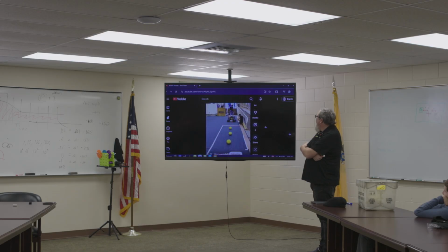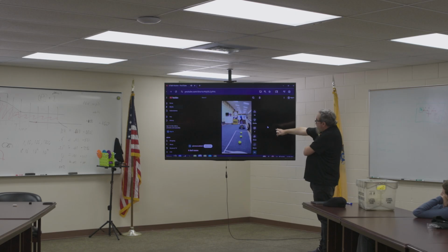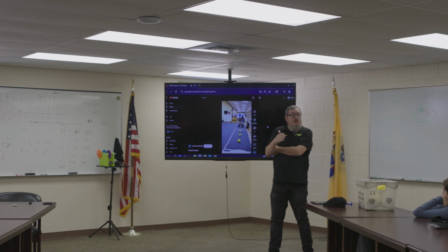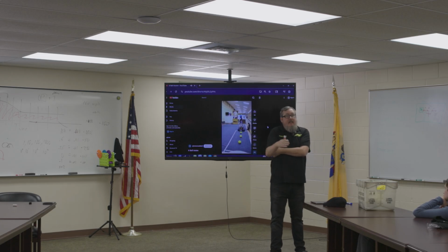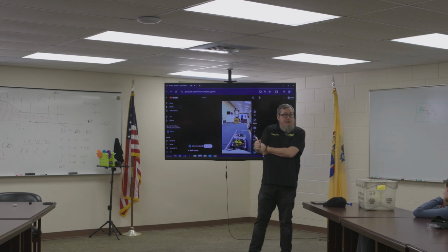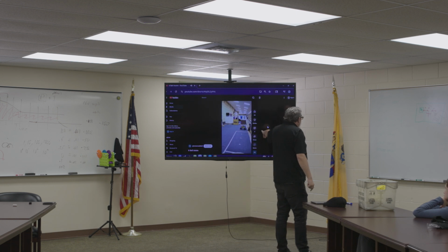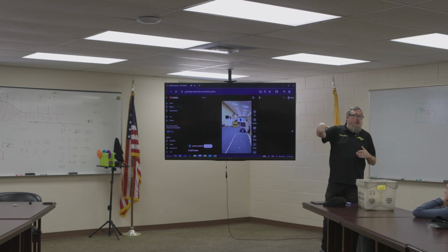So this is using a trapezoidal motion profile, so here, watch. It accelerates, goes at a constant speed, slows down, re-accelerates, constant speed, slows down. Whereas what happens with a P-loop? It'll wobble back and forth. If I am at 0 speed and I need to get to a certain speed, what happens? It accelerates very quickly, right? This controls that acceleration. So it's a nice smooth acceleration, constant speed, and a smooth acceleration down.